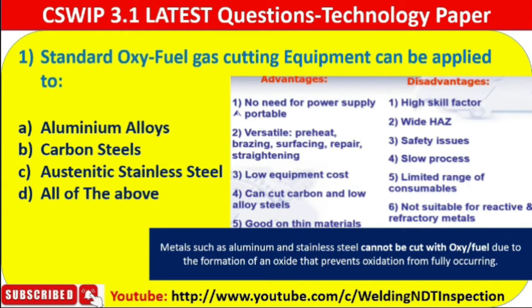Now the advantages of Oxy-Fuel gas cutting. No need for power supply. Portable. Just giving more information. Second, it is versatile: preheat, brazing, surfacing, repair and straightening. Low equipment cost, the cost is very low. It can cut carbon and low alloy steel.